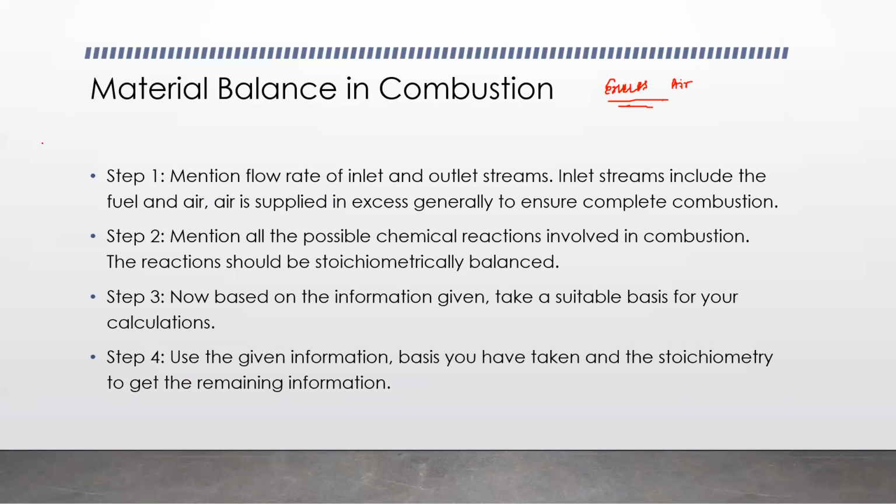Although in very rare cases you get completely 100% carbon dioxide. Some amount of carbon monoxide is always present. But yeah, we still supply excess air in order to ensure that maximum of the combustion that takes place is complete, right? So for excess air, you usually are given percentage excess air, or you need to calculate the percentage excess air. So it's either of the two things.